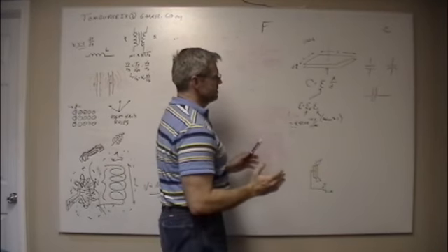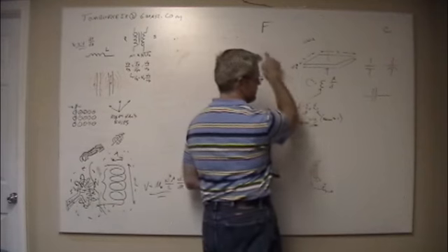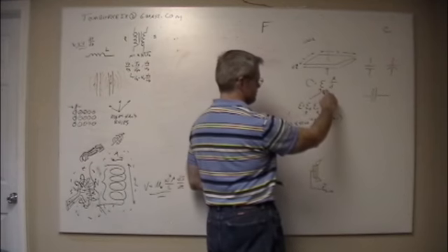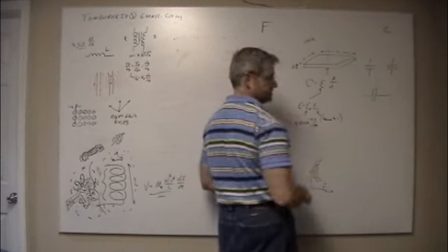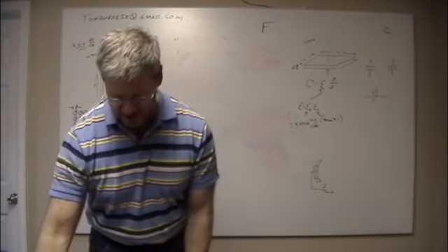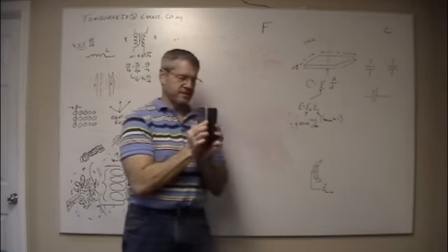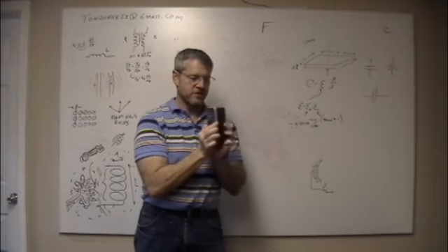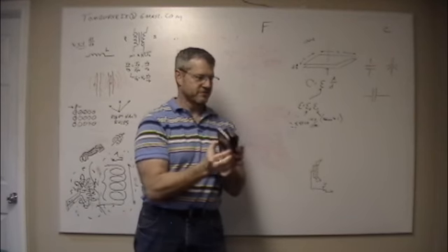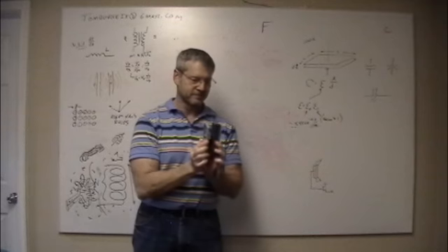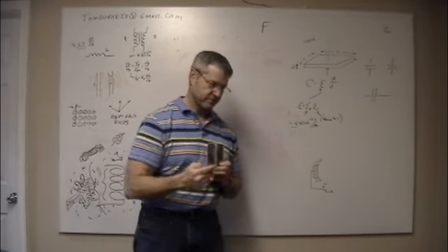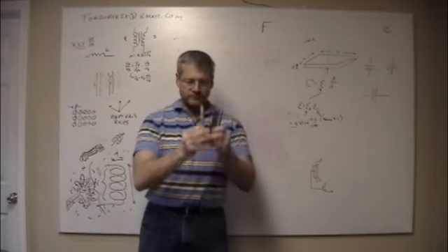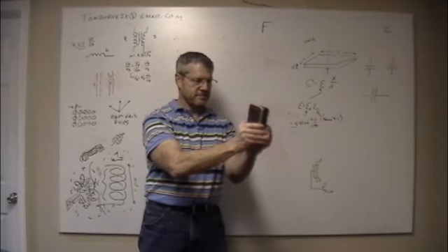A capacitor, the capacitance in farads is epsilon times the area of the 2 plates divided by the distance between the plates. When I say plates, it's literally something like this. So you actually choose the smaller of the 2 plates, right? Because that's going to be the limiting factor. And you kind of ignore fringe effects. There's actually some stuff that goes here. But they're actually 2 isolated plates.